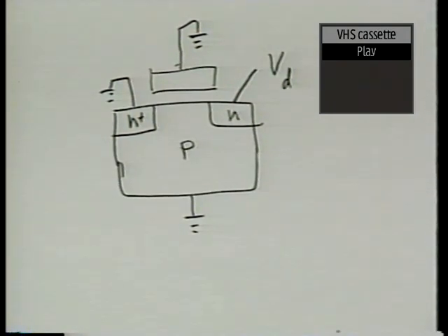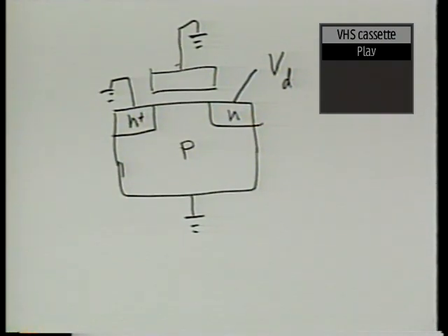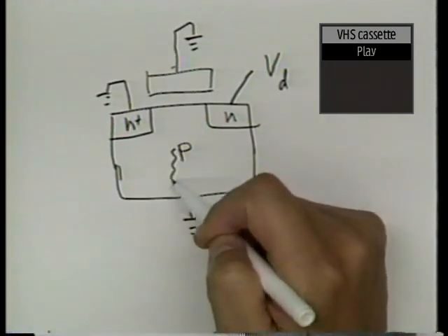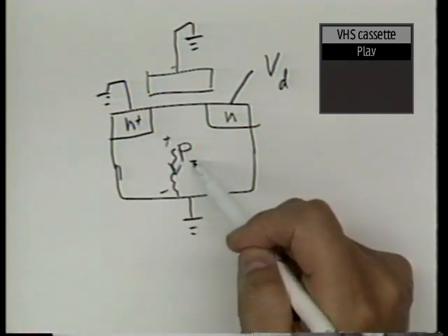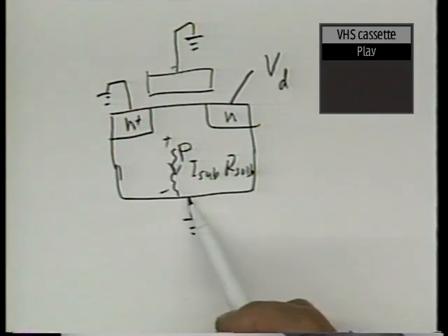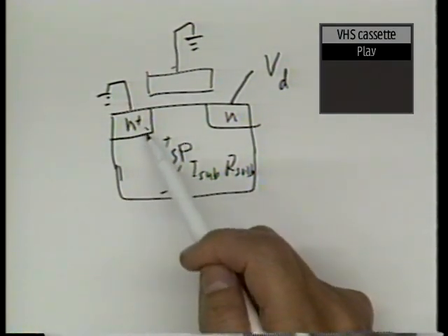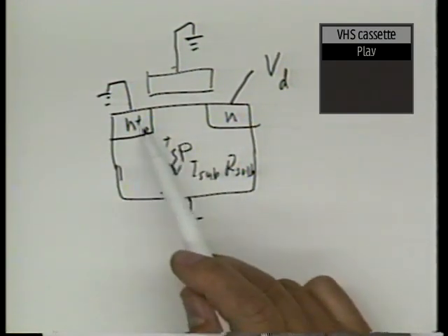I know you already anticipate a complicated answer, but the simple answer is, you should first say yeah, this should give us the higher of the breakdown voltages, is the correct answer, right? Because when the base and the emitter are shorted together, you should get the higher breakdown voltage. When does that answer become not valid? Well, that's when you consider there actually is some resistance in the substrate, such that when current starts to flow, we now have an IR drop equal to I_sub times R_sub. If the I_sub is large enough, even though the body is grounded and the source is grounded, these 2 points of the PN junction are not shorted to each other. If this difference is as large as 0.6 volts, then we know the bipolar transistor is on.